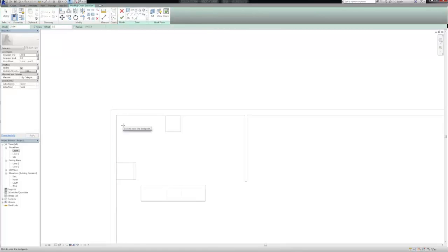To create an extrusion, start by sketching the footprint of the extrusion. Remember, extrusions don't have to come up from the ground. Instead, we can make a new work plane and make the form come out of the wall, for example. When the sketch is complete, we can set the properties of the extrusion. Set the extrusion so it aligns with the top of the components.